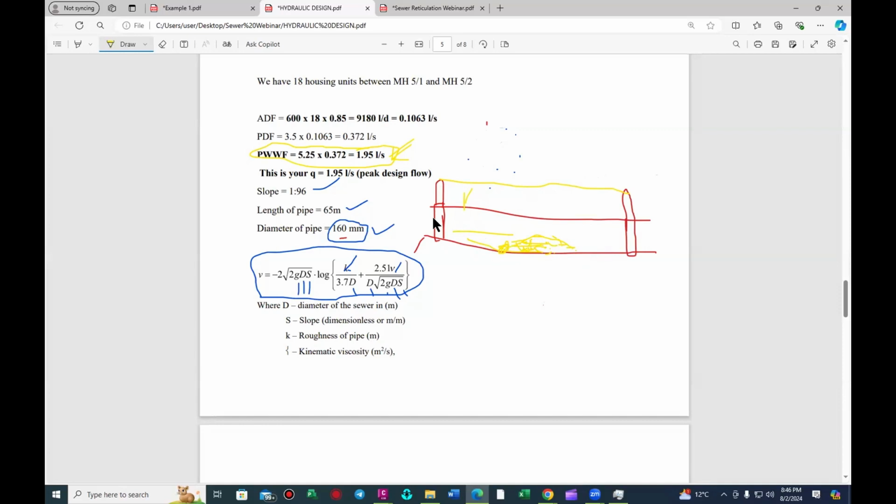Now it's 6 p.m. Everybody's back at home, everybody's taking showers. Then there is that peak thing that we talk about, the peak factor. When that peak factor happens, there's a lot of sewage being generated. Therefore, your sewer will achieve full bore velocity, because of that reduced diameter of the pipe, water is going to be forced to flow through just that small space that's left.